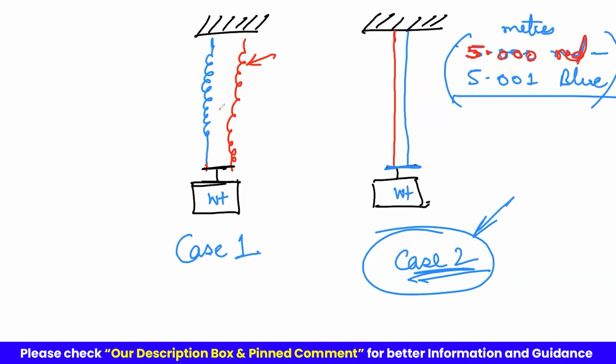Why is it decreasing? First of all, in the beginning I said it is a deliberately induced feature. It is not a natural feature of this governor. You deliberately induce this feature with the governor. That means when the load increases, the RPM has to decrease a bit. If you understand the working of the governor in the generator, there's a droop mechanism given inside the governor so that when the load is more, it automatically reduces its RPM. So that is given already.